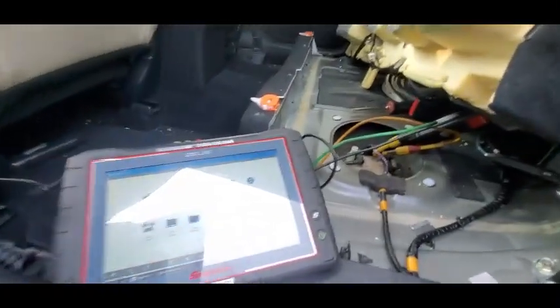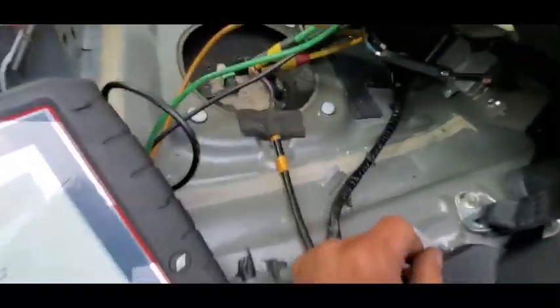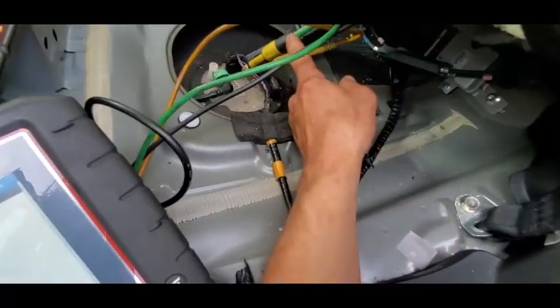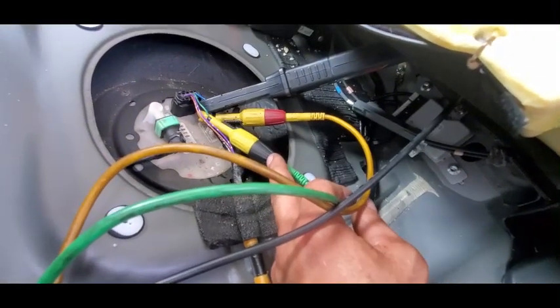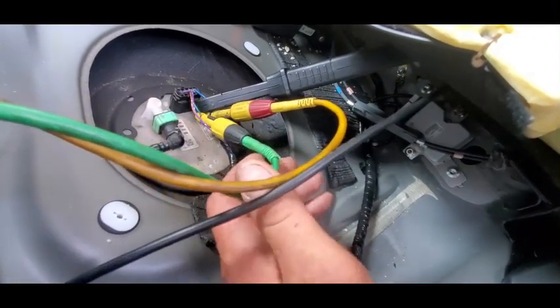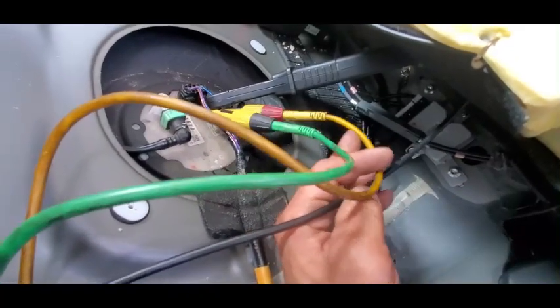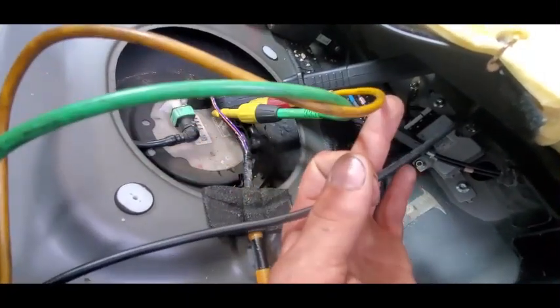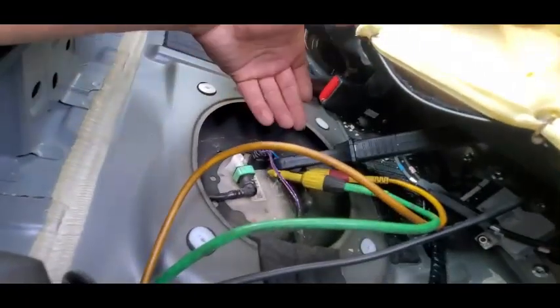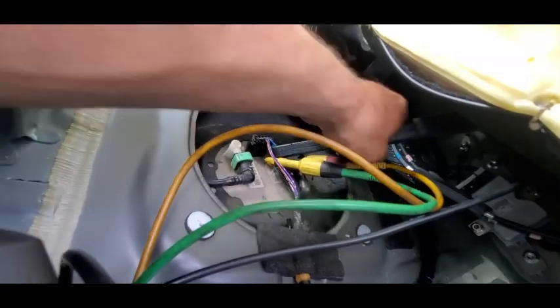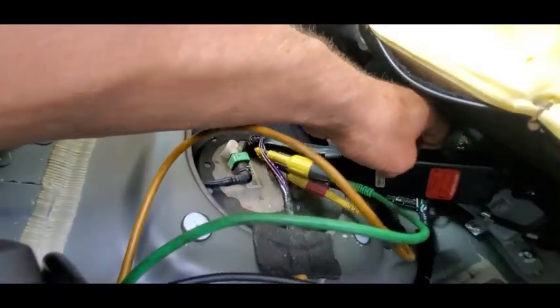All right, real quick rundown of how I've got this set up, okay? Our green trace here, I've got it pierced into the green wire, which is our negative side of the pump, and then our yellow trace is pierced into the blue wire, which is the positive side of the pump motor, coming from the module. Our amp clamp is wrapped around the blue. It doesn't really matter, it can be either or. And we're gonna turn it on to low amp 20 mode, okay?